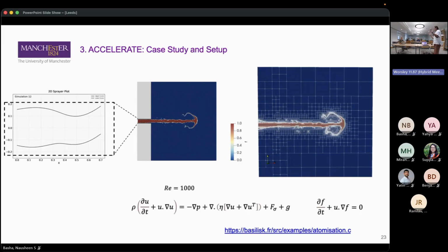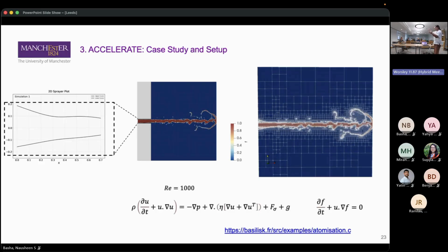On the order of 8, in the sense you start with a big block, you cut it in a horizontal and vertical direction. So that is 1. Then you take 1 box and then you cut it again, that's 2. So it isn't on the order of 8. So you don't see a lot of meshes here. They're like tiny dots because they are not zoomed in. But for the numerical solver to be stable for this kind of a problem, even if I had it at 4, probably it would be a problem, let alone triangular meshes, it would lose a lot of flux. Thank you. Okay.